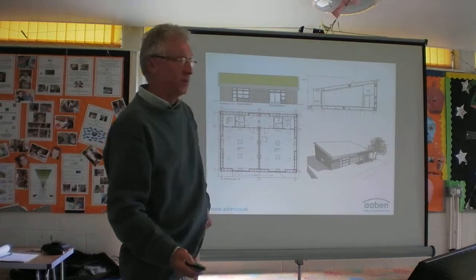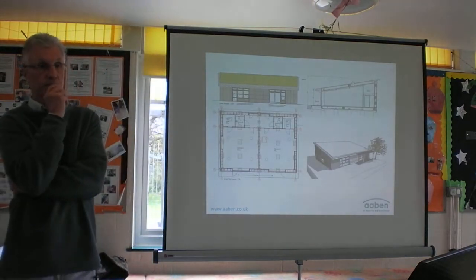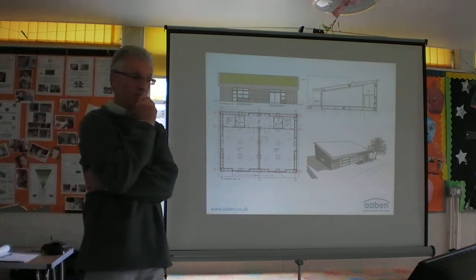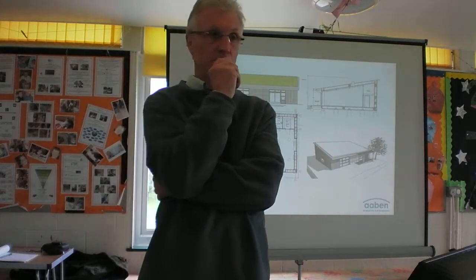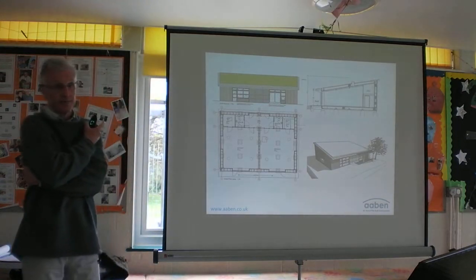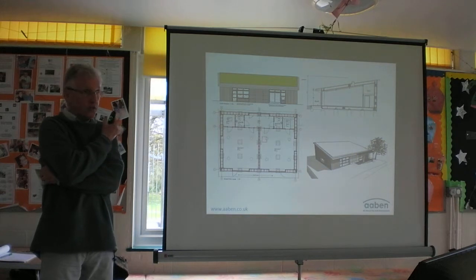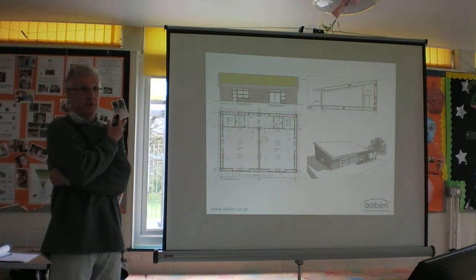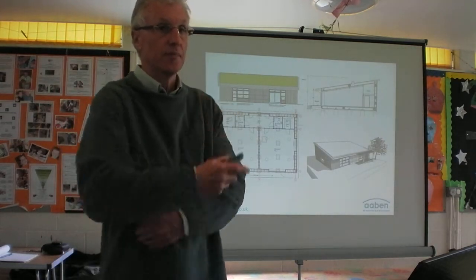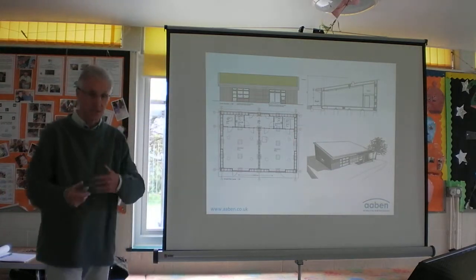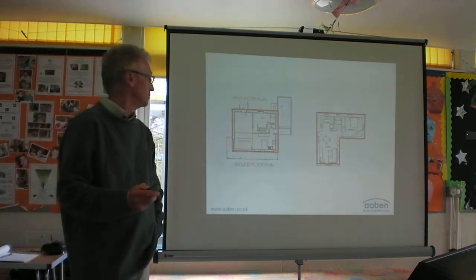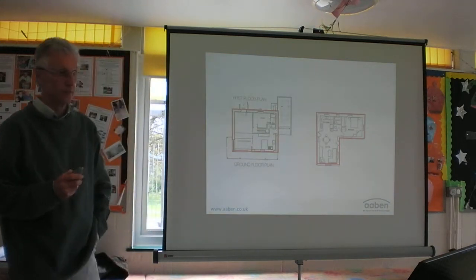Would I be right in inferring from that, because it's essentially a passive system, the costs of incorporating that are not great compared to a ventilated system? You've still got a ventilation system in here. You've got to have one. No, for winter, I mean an assisted ventilation system. Yeah, you've got to have mechanical ventilation in a passive house because you've got to deal with the winter cooling issues, which are heat loss issues. I guess the question is, what are the cost implications of having a passive system? Not a lot. No, it's a design issue rather than a maintenance cost. Exactly. It's lower cost to run by a long way.